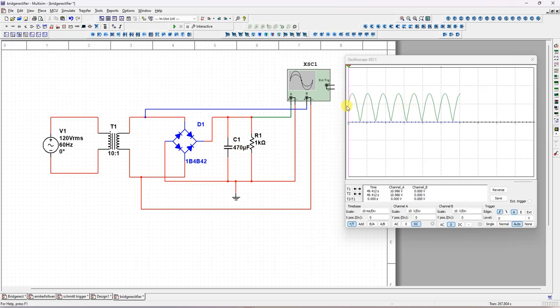Once you connect the capacitor, first the capacitor will charge, next it will discharge, charge, discharge, charge, discharge. Instead of this waveform, this is ripple content. DC means what? Straight line. This unwanted AC present in the output we call ripple content. So using the capacitor filter, we are removing this ripple content. So the output can be a straight line only. Let me check the output now.